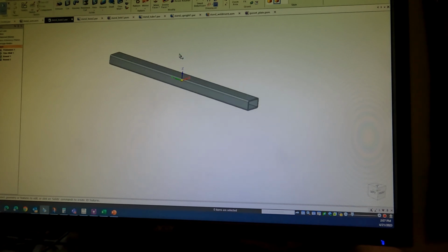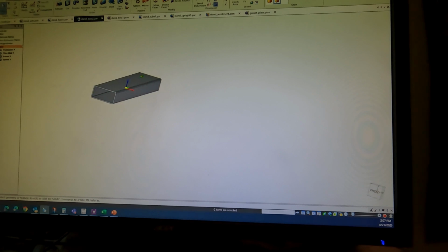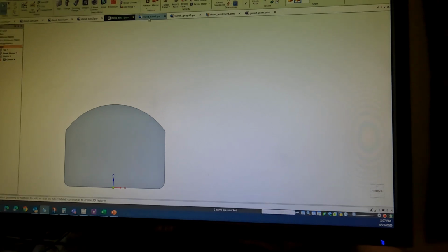We're going to make this out of steel. The reason being that steel is very strong and it's actually somewhat affordable. It's not the lightest. So when we get into our design optimization, maybe we want to look at something like aluminum instead of steel, which might be lighter, but a little bit more expensive. Those are the kind of trade-offs that we'll have to get into as we refine our design. So you start modeling the different individual parts for your design. In this case, it's a lot of different shapes of tubes and brackets and different sheet metal parts.